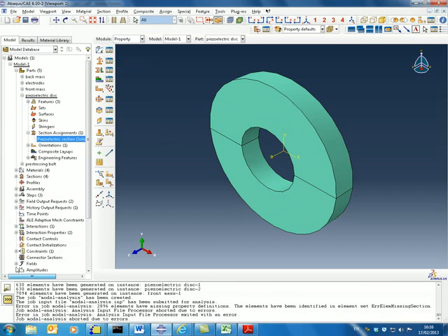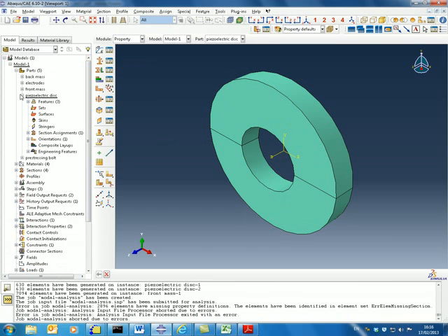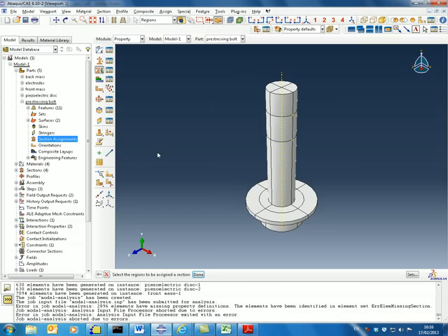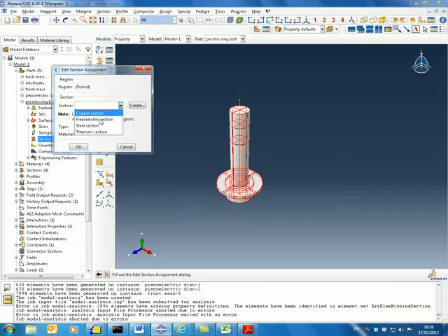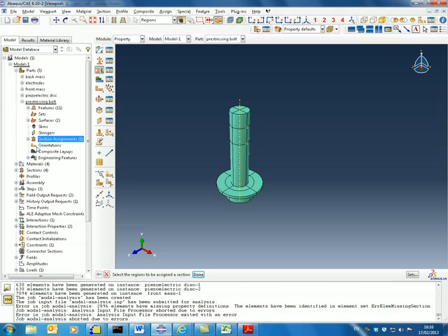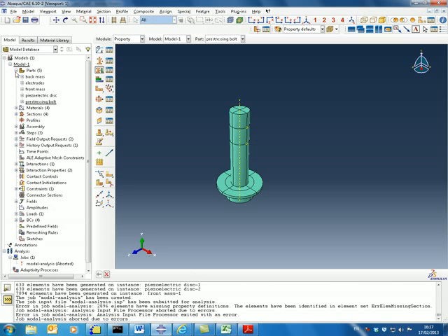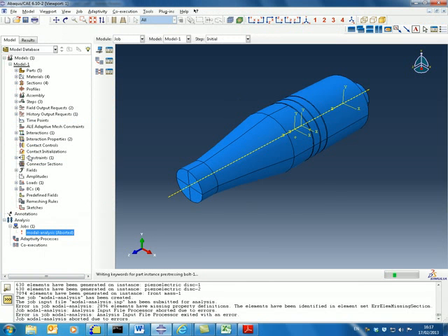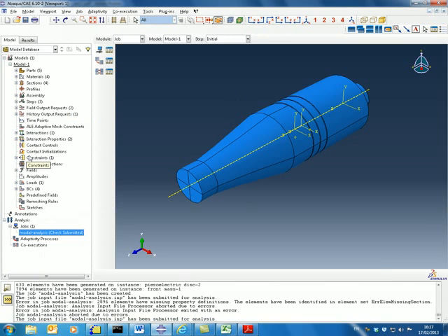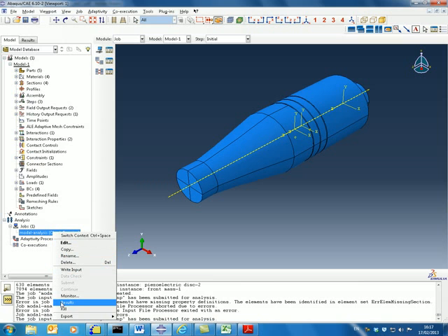Piezoelectric disc is correct. The prestress bolt, we forgot to assign the section for it, so double click on assign, select the bolt, and then the titanium section. For that reason, it's important to check your input file before you submit the job. Otherwise, you submit and keep waiting, and these mistakes can give you an error and stop the analysis.